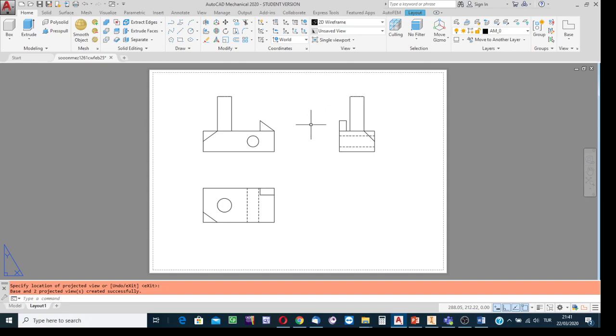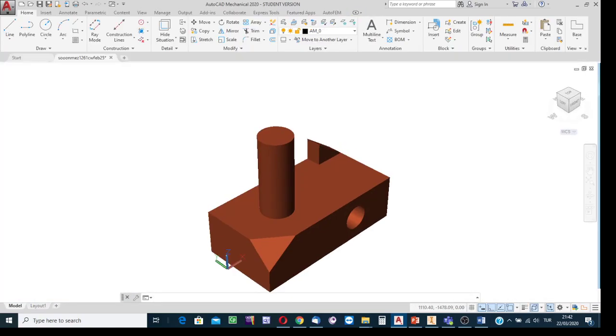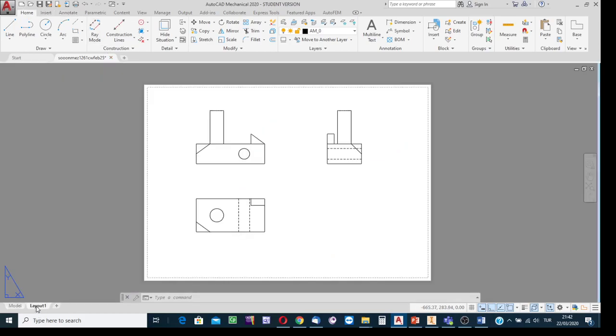To be able to show the symmetry axis, for horizontal and vertical axes, we use the two-dimensional tool of AutoCAD. So I'm going to make a switching. I brought the cursor to the status bar and found the switching facility. Click on the listing arrow and select the mechanical option. It is to change the mode from 3D to two-dimensional mode. Okay, and then click on the layout tab to see the created views again.